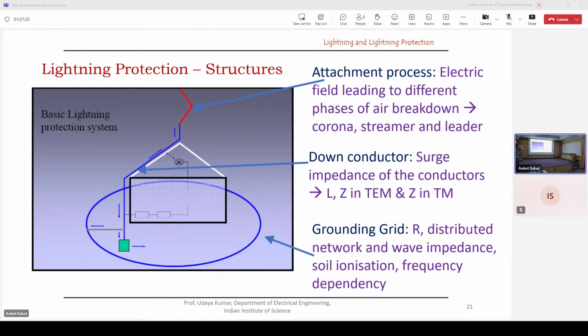Yes, Benjamin Franklin thought about this 200 years back or more, not in a correct way, in a wrong way. You put an air terminal, either a wire put horizontally or vertical rods, so that the lightning will see it first in its course, because seeing is not really possible. Then provide a so-called low impedance path to ground, and try to dissipate the current.